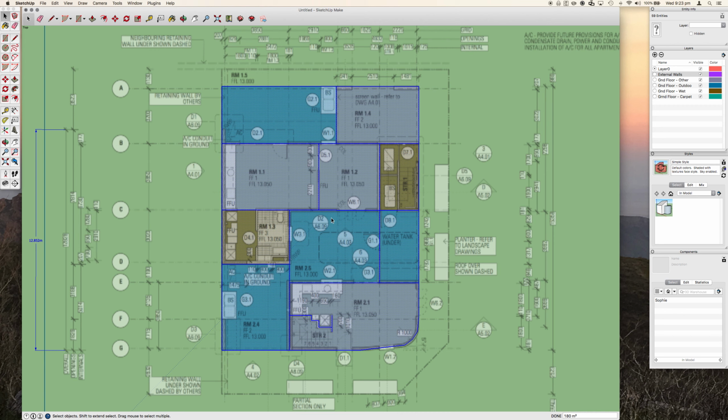And then in terms of making a determination of your windows, there's a couple of ways of doing that. For small resi, you'll often get a window schedule plan, and you can just drop that into SketchUp, scale it, and do something similar, and you've automatically got your window areas. Then you just remove that from the wall area. If you want to get more accurate, you'd remove your door openings as well, which I think's wise to do.